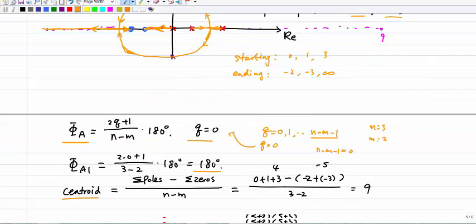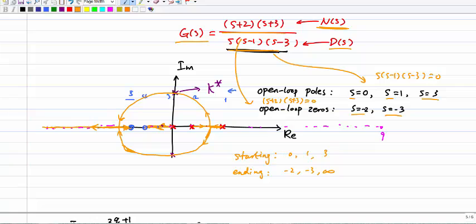Okay. So apparently, as you can see, as k increases, this one is going to move to this zero. So it's great, which means it's going to the left half plane. And it's also good for these two, because they have to split and gradually move to the left half plane. One goes to this -3, one goes to -infinity. So there's a critical k value called k star over here. Once it's past this value, greater than this value, it's going to move to the left half plane. So we can see this will be stable for some big k.